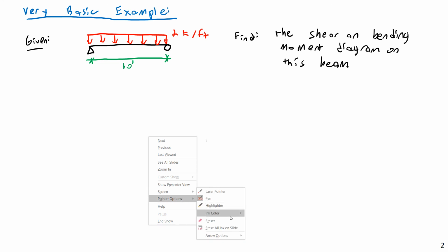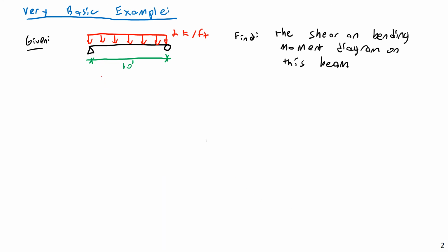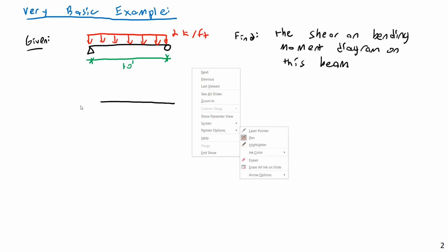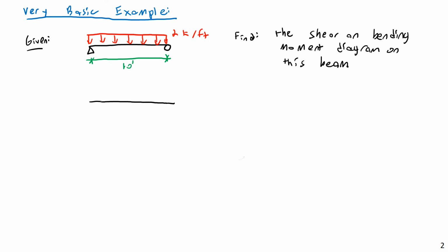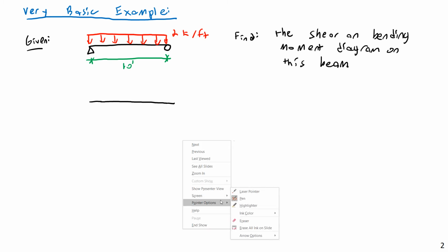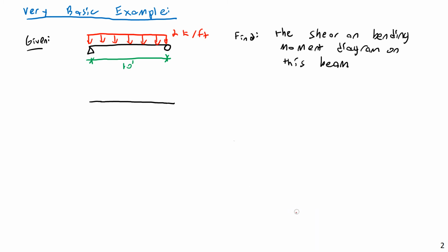So first of all, the first step is going to be to solve for the reaction forces, and because this is a symmetric beam, I can show a global free body diagram very easily. There are going to be no horizontal reaction forces on this. Hopefully that's fairly straightforward. I'm not showing it cut yet, just in its entirety, a global free body diagram. If I wanted to solve for these, I could show an AY and a BY.